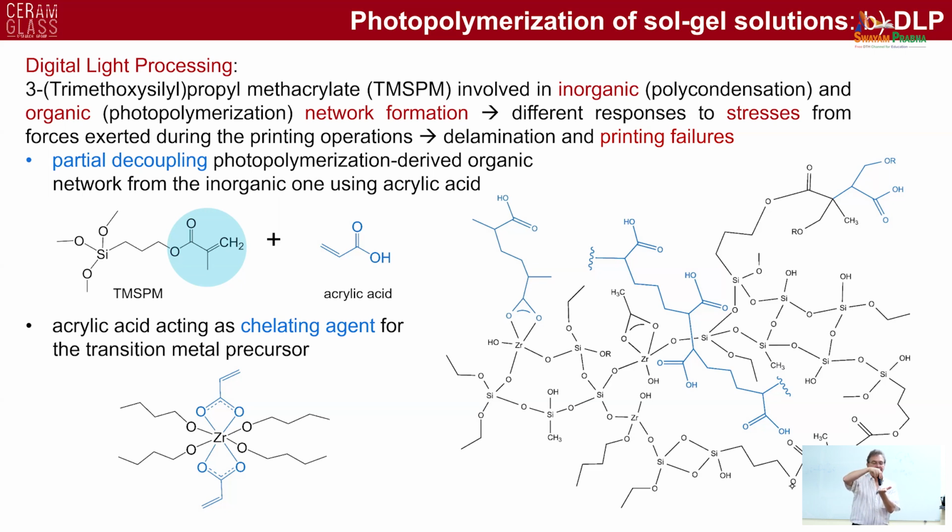So the issue is that there are adhesion forces between the printed part and the surrounding liquid. So if the strength of the printed part is not good enough, the part will break, or if the attachment to the top of the moving stage is not strong enough, the part will detach. But this you can solve. The strength of the network that you have formed needs to be sufficient for allowing the pull-up.